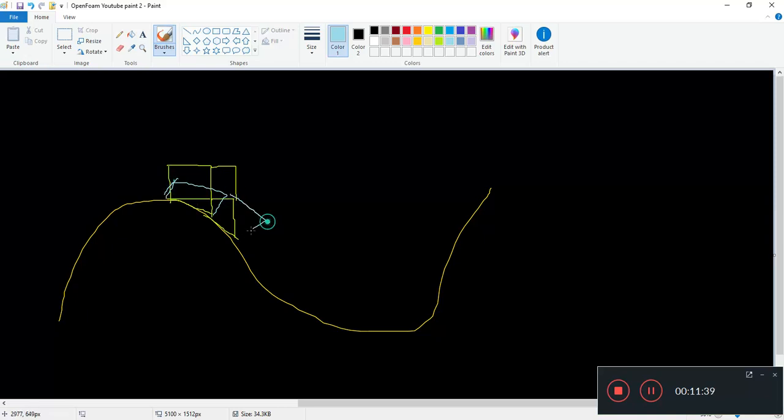Hopefully you have layers that conform to the surface. And of course, the natural way is for layers near the surface to be very fine, right? Because you want to resolve those. But as you go out of the surface, the mesh size increases.